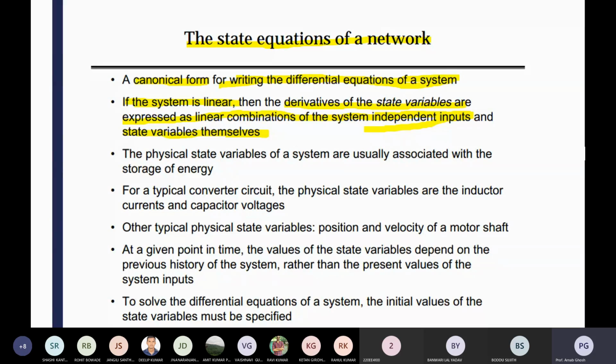For that modeling, I told you that there is no driving force, meaning D is 0. The change of v-hat in, meaning the input voltage, you are making it the AC portion of the input voltage, v-hat in, is 0. For what? Because you are providing the driving force, the input driving force. That force is responsible for the independent inputs, that is v in. So you are forcefully making the AC portion of the input voltage 0, so that D of that equation is 0.